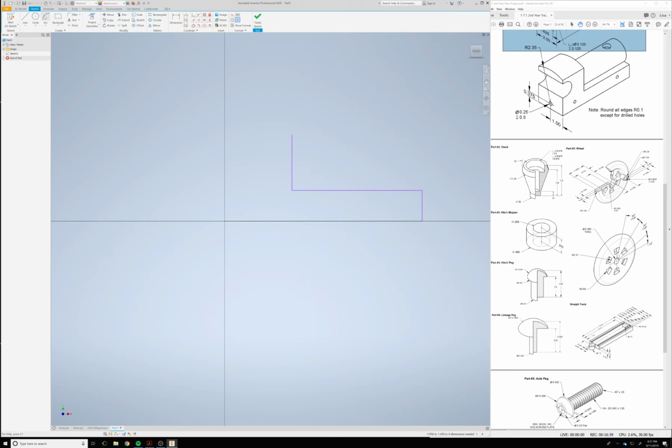I'm then going to put in an arc from the origin to this corner, and I don't know exactly how I'm going to have it, so I'm not going to put any dimensions. Let's go ahead and dimension this now. This is going to be 0.55 in total. Okay, total length from left to right, and this right here is going to be 0.5. Okay, I'm sorry, it's not 0.55, it's 0.65.